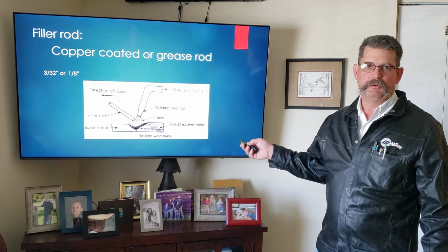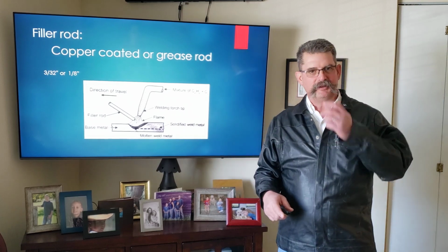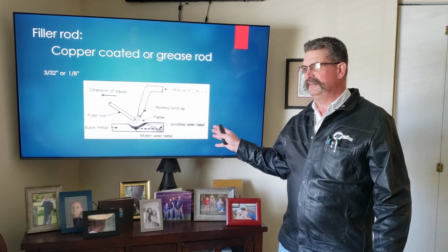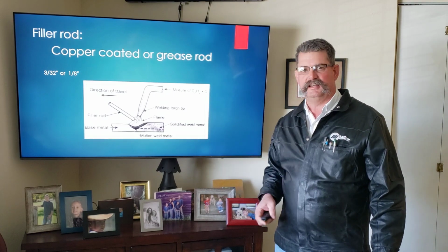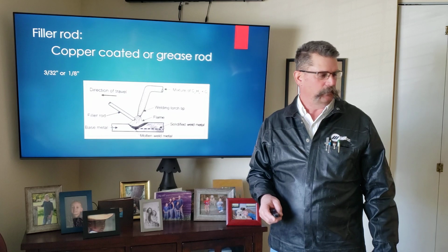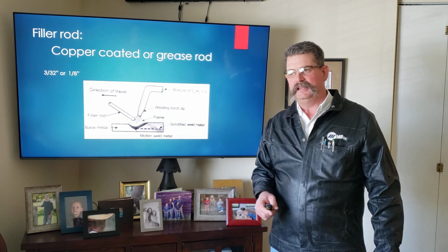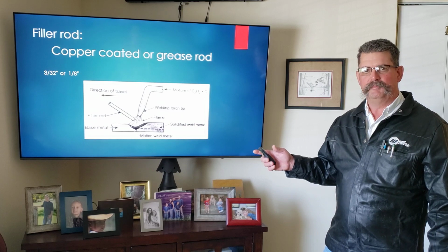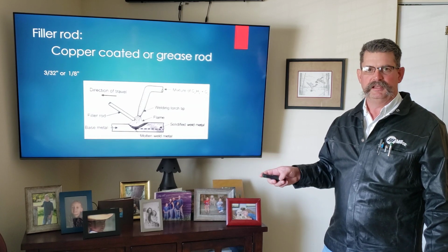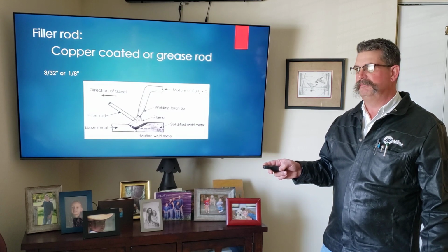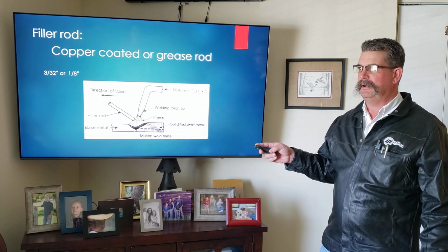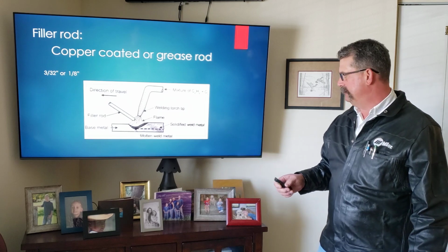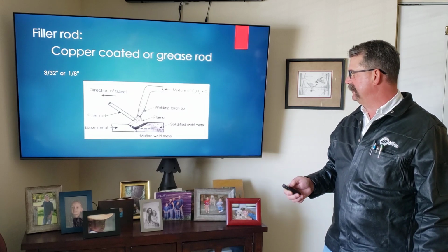One of the most important things in practice in terms of having students do these kinds of things out in the lab, I think where oxyacetylene welding is still really important, is that it teaches students to maintain a weld pool. It illustrates to them the importance of having the proper heat introduced into the weld. And that's the beauty of learning oxyacetylene welding.